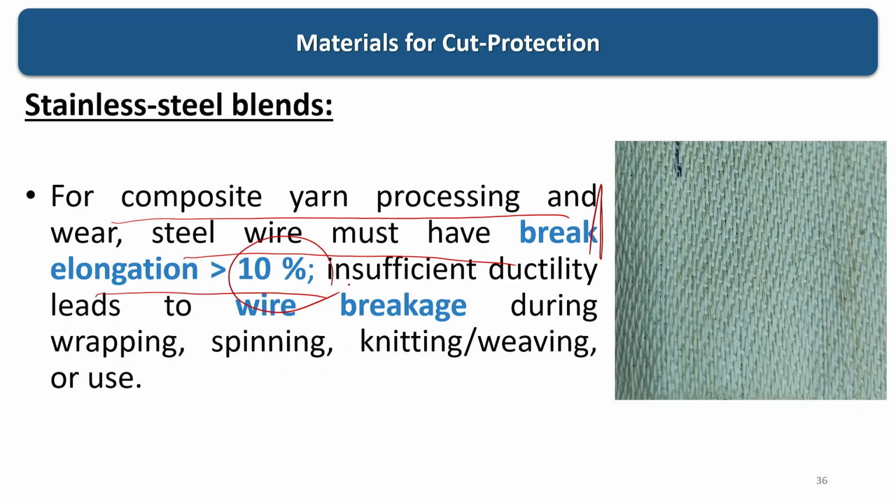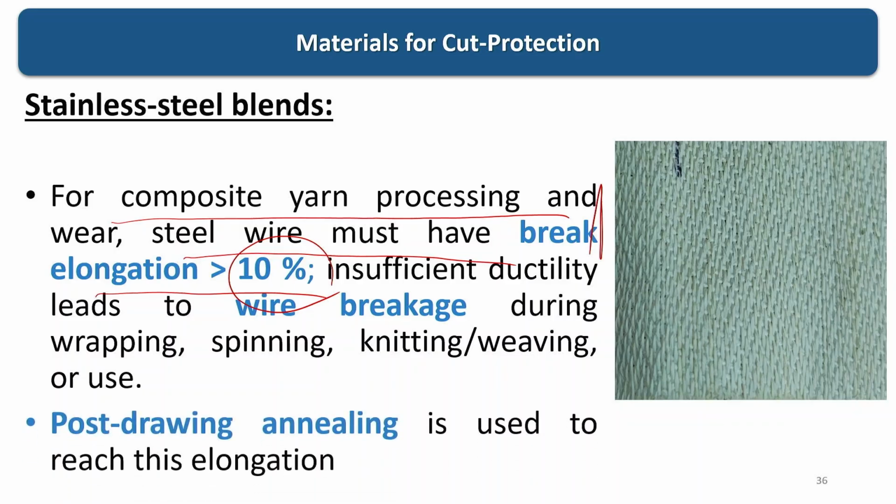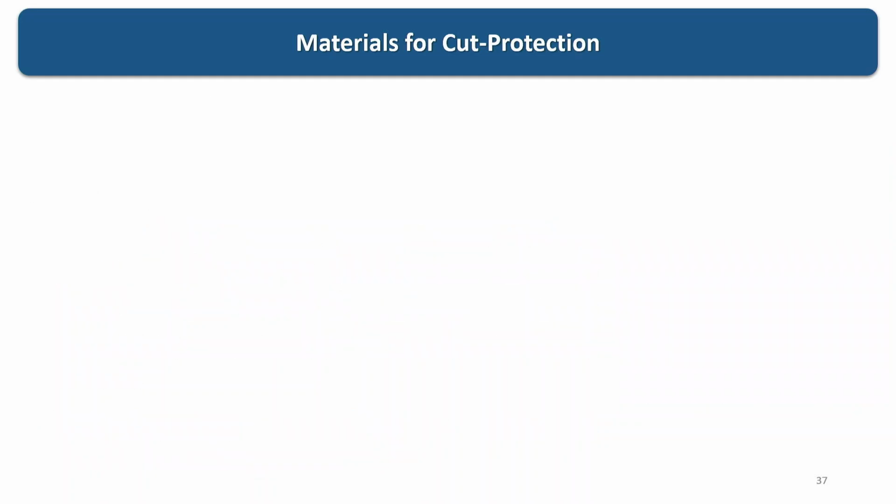Sufficient ductility should be there. So, post drawing annealing is used to reach this elongation. Annealing is required after drawing to enhance the elongation.